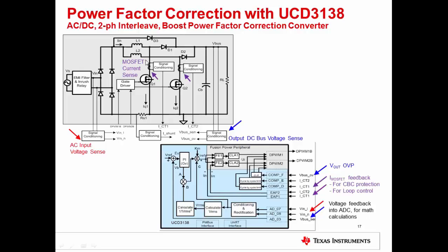The current in the power supply is sensed using current sense transformers and presented to two independent front-end blocks. This allows two front-end blocks and two hardware peripherals to be used independently to control two current loops. The same signal is also presented at the input of analog comparators for providing cycle-by-cycle current protection. In terms of the output, signals coming from two DPWM blocks are 180 degrees phase shifted to control the two interleave power MOSFETs.